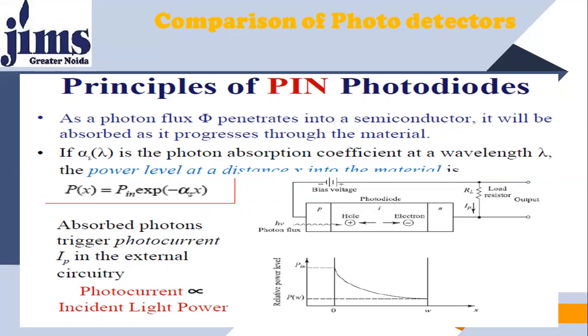This is the maximum power, because when photons impact the electrons, some time is required to get fully free electrons, and then you get the full photocurrent. So this equation gives you the idea that it's a sinusoidal type of process. Because of the absorption of the photons, you have a photocurrent, and IP is the photocurrent flowing through the external circuit.